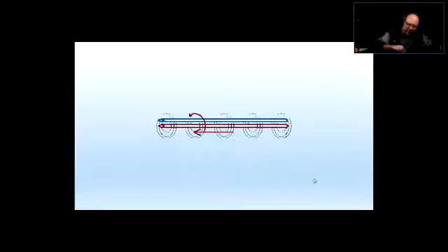Sometimes we want this thing to happen in the transformers, yes, we do, and sometimes it works against us. When it comes to telecommunications and using data or telephone or any kind of signal wires, this is not such a good phenomenon for us to be happy about. So now the current is going to flow in the same way if the conductor is placed in close proximity in a way that the electromagnetic field is going to affect that other conductor. So in telecommunications, we call this thing crosstalk.